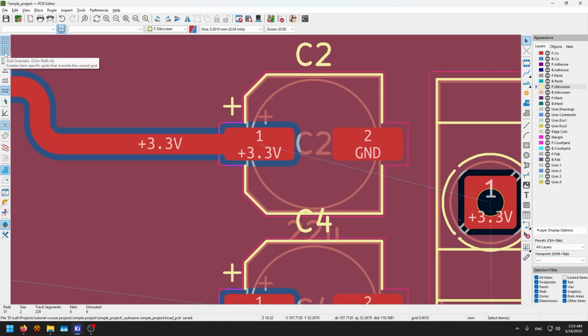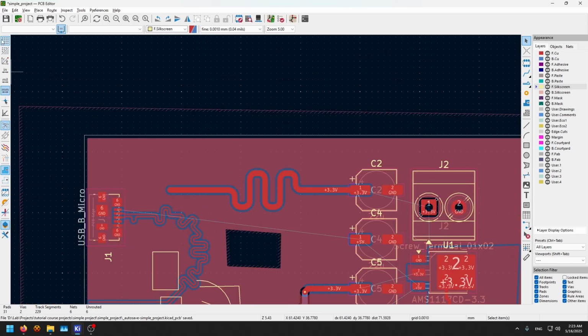And now let's go to this area. This shows the grid or not. This thing is, if you have some override on the grid, it can show them. Here is, instead of x and y for your measurements and stuff, you can use the radian system. Really, I don't recommend that. Here you can choose inches, mils, or millimeters. For me, I choose millimeters. I recommend you do that.